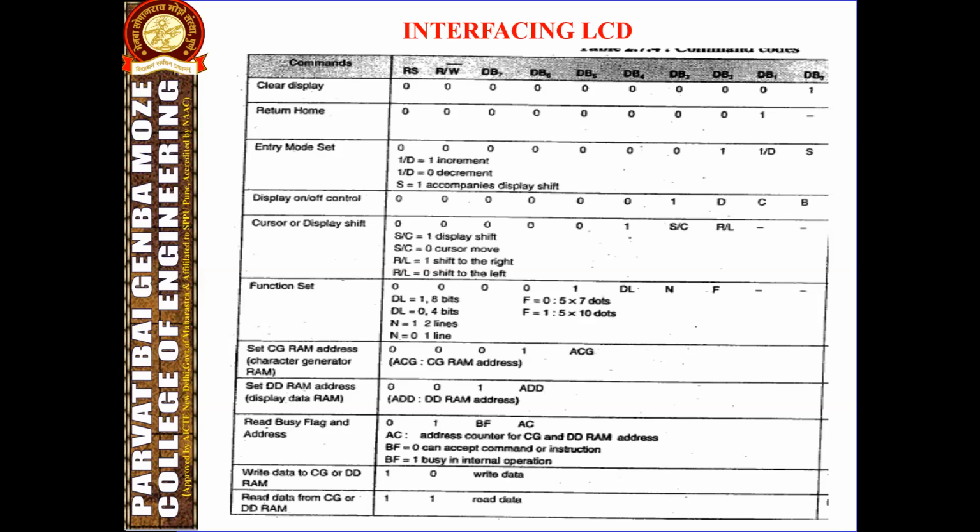So before initializing the LCD, an algorithm is required to initialize and write to the LCD. First of all, wait for a second for the display to stabilize. Initialize the LCD by giving the instruction 0x38 to the command subroutine, and wait for 5 milliseconds. Then issue the command 0x0F to the command subroutine for display on, cursor on and cursor blinking, and after that wait for 5 milliseconds and issue the command 0x01 to the command subroutine for clearing the display.